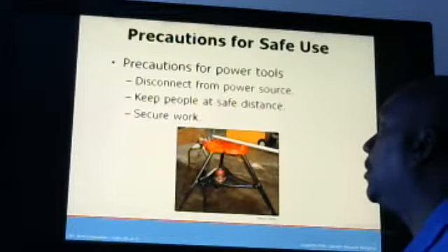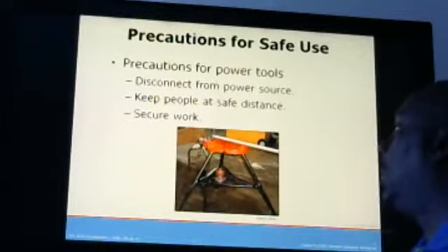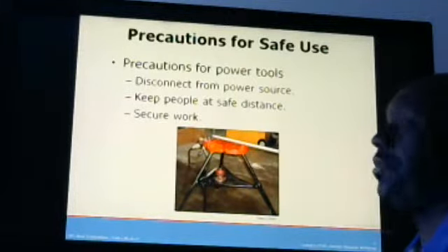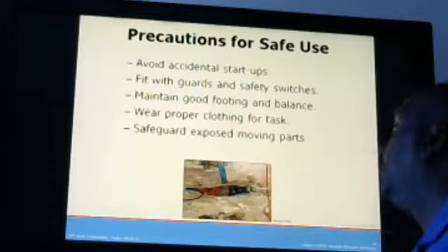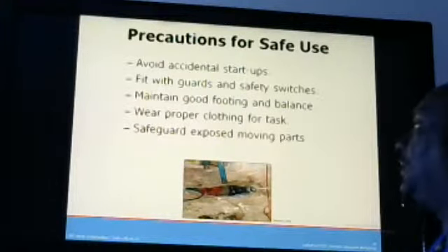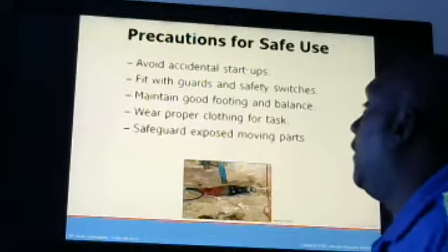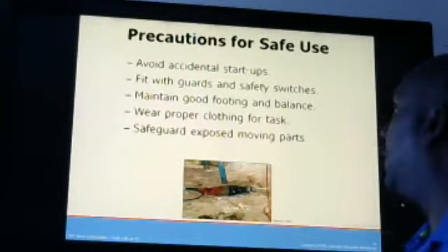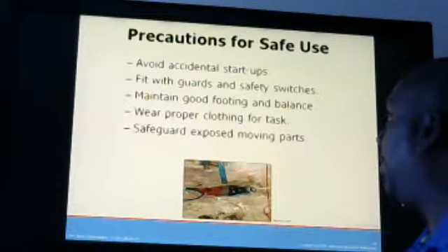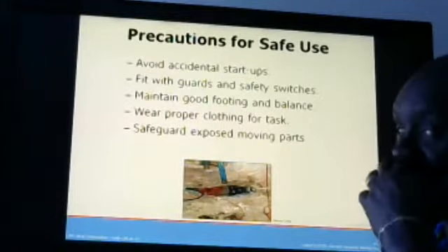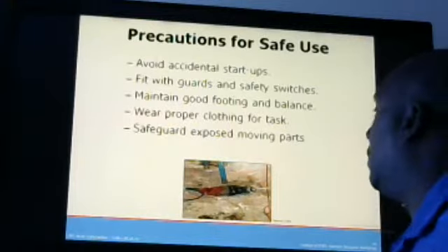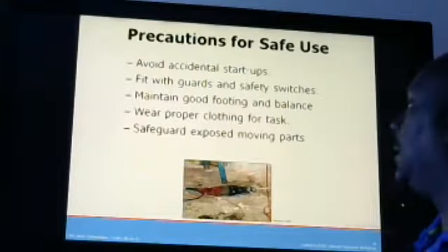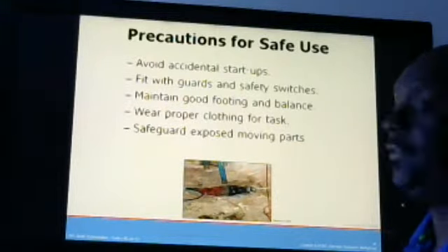Precautions for power tools. Disconnect the power source. Keep people away from it. Make sure that they are a safe distance away. And make sure that you secure your work area. Avoid accidents in starting up. Fit with guards and safety switches. Maintain good footing and balance. Wear proper clothing for the task and safeguard exposed moving parts. You want to make sure that you're always doing things that are going to keep you safe.